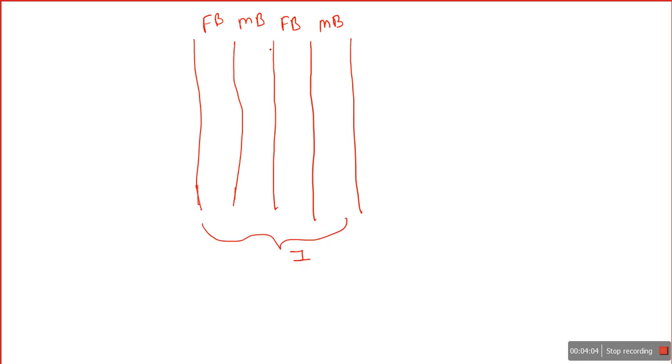So it consists of a set of fixed blade which is followed by a set of moving blade. And I have told already that in case of reaction turbine, the nozzle is replaced with the fixed blade, and the cross sectional area between two blades is varying.